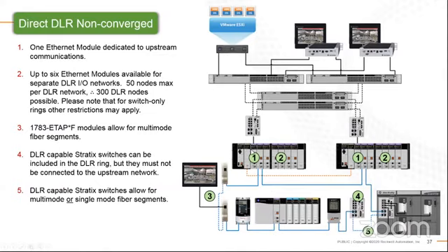One of the things that you should be aware of, if you haven't seen that in the design, is a swap over will happen from your primary to your secondary if you have a loss of power, if you change anything within the code, and also if you have a drop in communication on that chain. So what we typically see in these type of architectures, and what our recommendation is, if you can have a Stratix, potentially maybe a 5700 switch, dedicated directly to the chassis A, chassis B, have it separate, and then do your resilient network up top in maybe a redundant star topology or some type of ring topology.